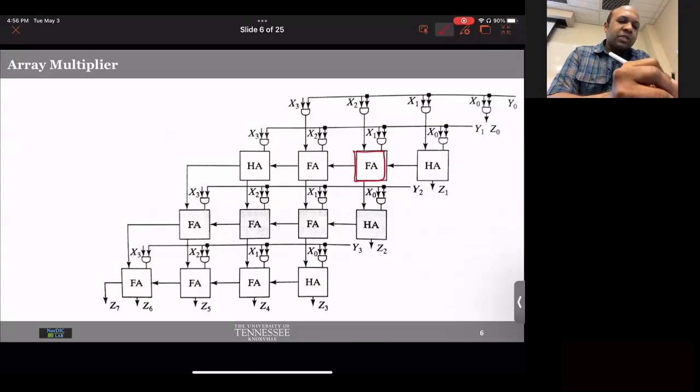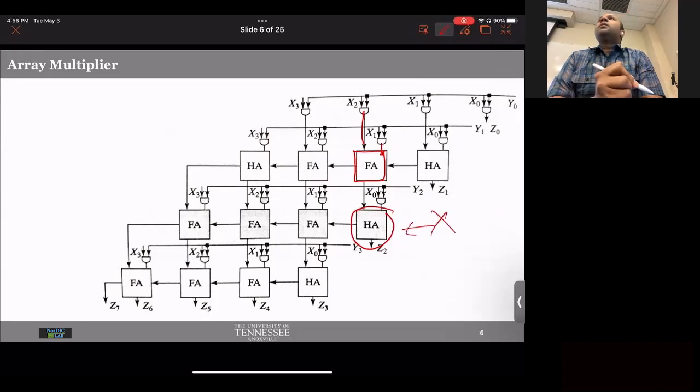So you see, using this full adder, we are first adding the first 2 bits. Okay, and then we are using another adder which doesn't have any carry in. Right, there is nothing there to give it a carry in. So this is a half adder which takes in the sum of the first 2 addition and the other bit. So basically, we are adding this 2 again with that half adder.